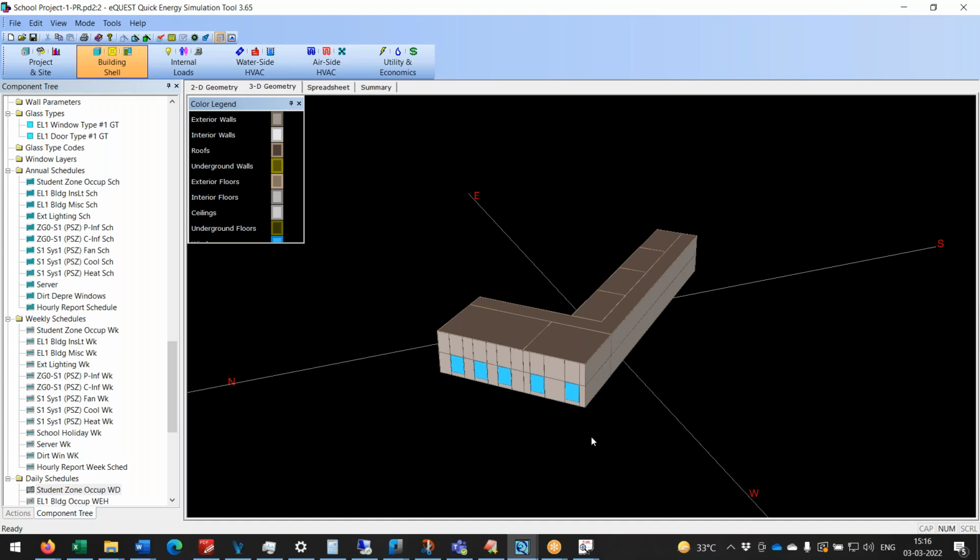Design builder, obviously you have to get used to the software. For design builder, the backend engine is Energy Plus, which takes a bit more time when you're simulating, and it can obviously throw up some errors. So it's all about how user friendly it is, and of course, Energy Plus is accurate. The accuracy level of Energy Plus is comparatively higher in comparison to eQuest. But yeah, these are the major advantages eQuest has. One is that it is very quick and it is free.